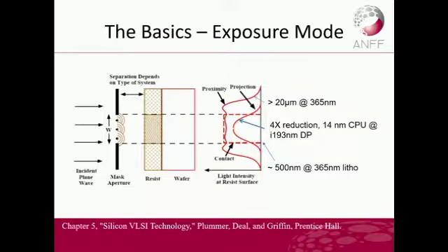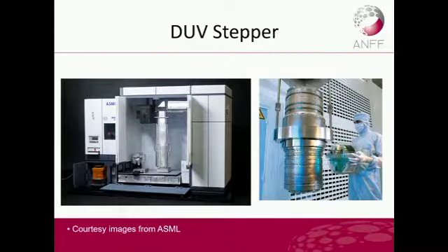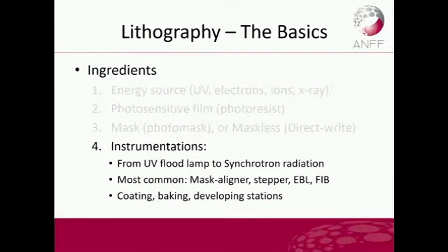It's very complicated. And if you think about the type of optics required to make this sort of projection, I'll just show you a picture of a scanner from ASML. You can see that it's actually a very complicated piece of electronic optics. The lens is probably as tall as a human. And this is the old technology, by the way. This is the 193 scanner. If you look at the current EUV scanners, you can't use through transmission. Everything needs to be reflective. That's why the systems are so expensive to make and also very hard to maintain.